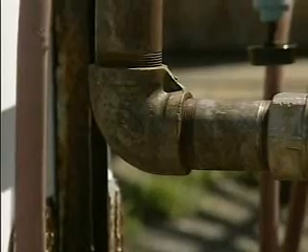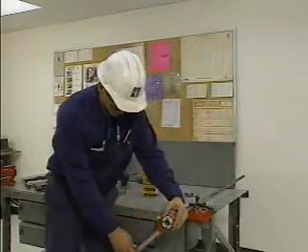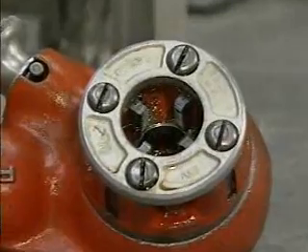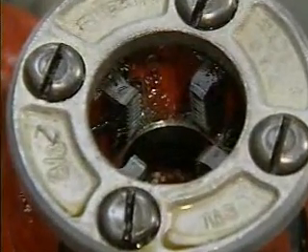A variety of sizes and types of individual pipes can be connected by joints and fittings to form a larger piping system. Before the pipe can be installed, the length of the pipe that you need must be determined. The pipe must be cut to size, and the pipe must be threaded. In this part, we'll see how to use a pipe die to cut threads on a pipe. The threads of a pipe are created with a pipe die. A pipe die is a tool that has teeth that cut into the outside walls of the pipe to form threads.